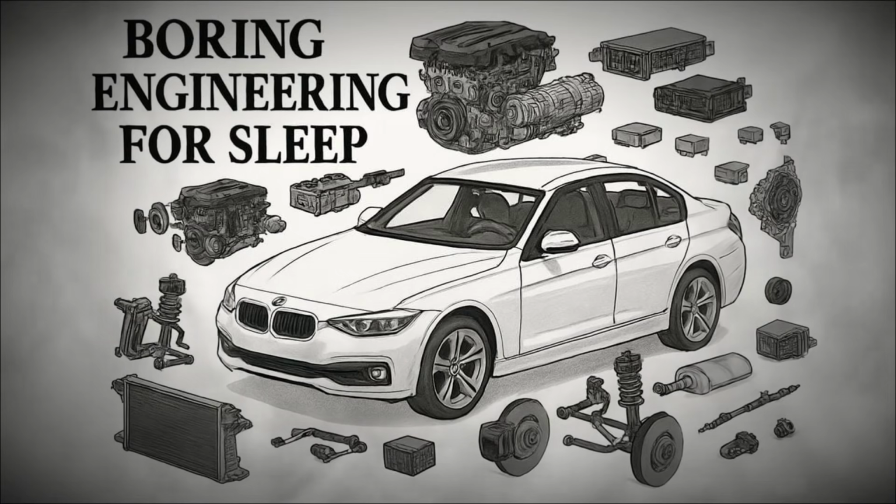The suspension system must also be durable, since it constantly endures impacts, loads, and stresses. Components such as bushings and ball joints wear over time and require replacement to maintain proper function. Alignment of the suspension is also critical, as incorrect angles of camber, caster, or toe can lead to uneven tyre wear and poor handling. The importance of the suspension system extends beyond comfort, because safety relies on it as well.